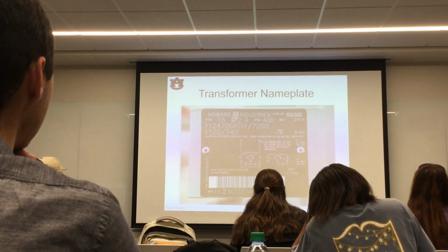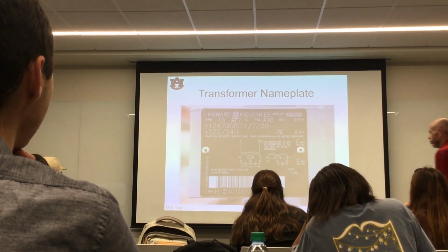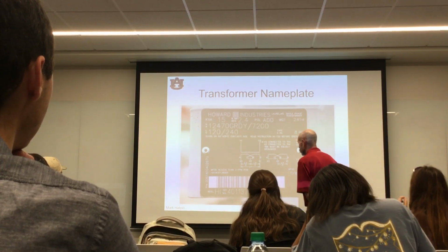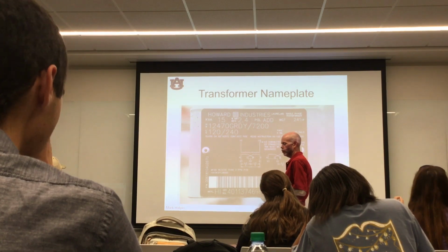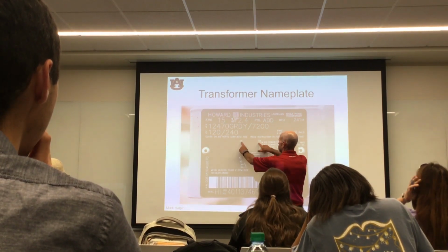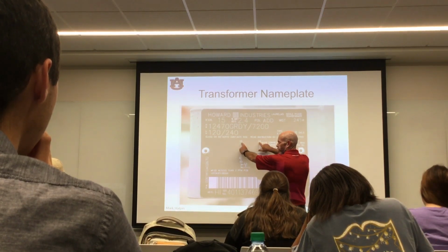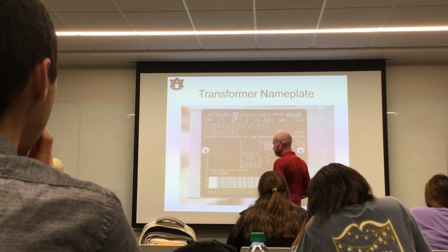Well, we got all kinds of good information. Now, one of the things I can point out to you is, for example, we talked about how transformers are wound, and some of the notation that's used. Remember I told you about H's? H's are for the high voltage winding, and X's are for the low voltage winding, okay?